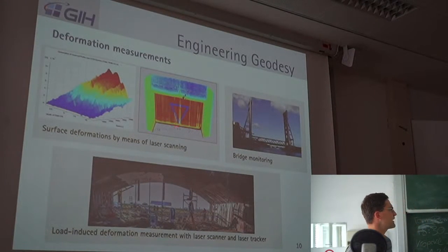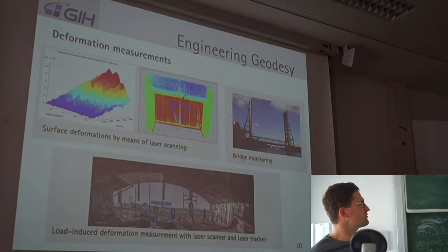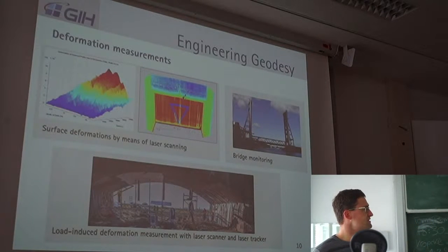You see the deformations when the water is in. Then the gate deforms. You can see it here in this plot. It's in the range of some meters, it goes in this direction. This is 1 meter deformation, and it's a lot.